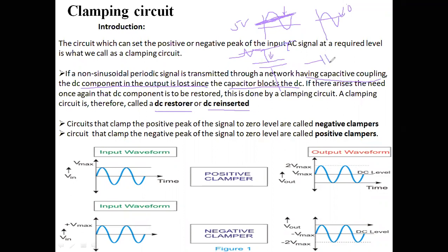When it is an AC high pass circuit, like this, the signal has to pass through the capacitor to enter the next level. Therefore, this capacitor is going to block the DC component. That's why, when we discussed the high pass circuit, especially with the square wave, I mentioned that if the time constant is very large, the output will be similar to the input except the DC component is 0.